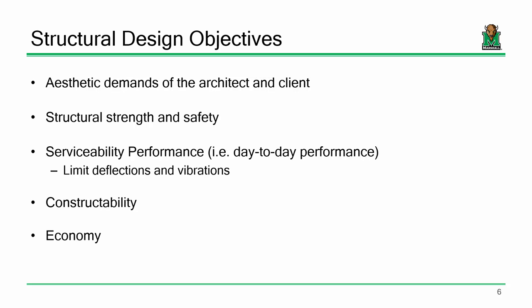Well, those beams, not only do they have to be strong enough to support the loads they're being subjected to, they also have to be stiff enough. The difference being that they can't bend or deflect too much. Now those are two different scenarios. Those are two different questions that need to be answered. And what you might find is that in some instances the beams have really sufficient strength, and what's governing them is the fact that they're deflecting too much.